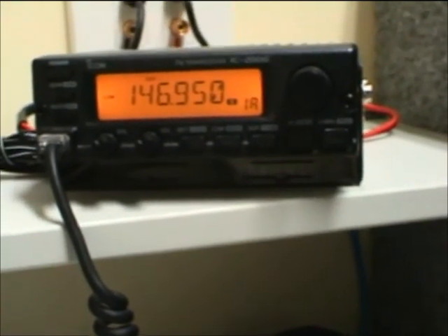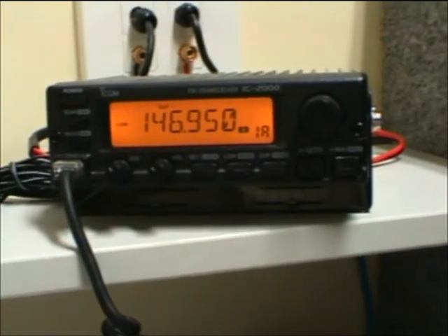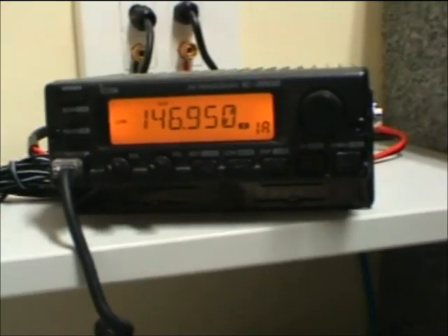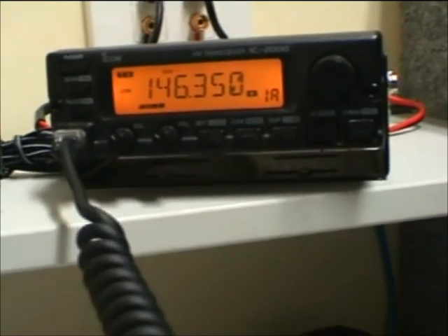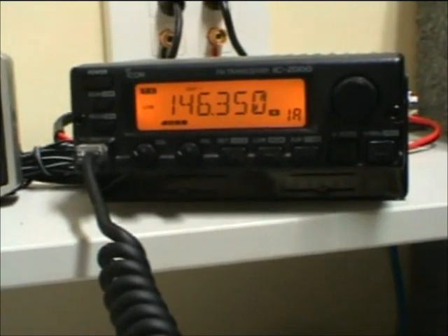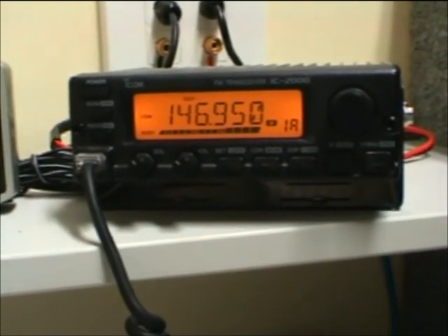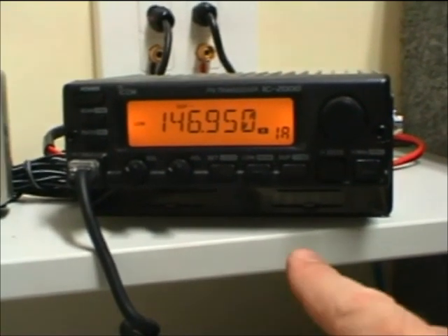So when there's no signal present, you've just got noise coming out of the frequency demodulator or discriminator. The set automatically detects that noise and shuts the works down. If we trigger the local repeater, I'll just put a call out to say I'm listening. ZL2 Tango Whiskey testing on 14695. So you can see when the carrier is coming back.